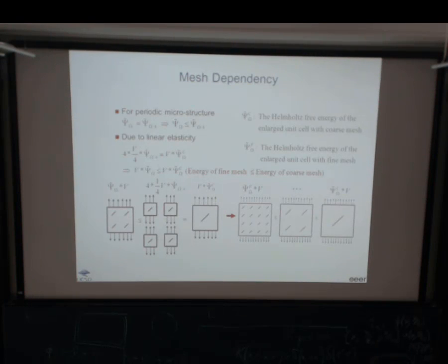So we try to use this to explain the mesh dependency. I know I'm going an unconventional route, but I think this offers a different explanation of why in damage mechanics there's mesh dependency in the numerical solution. So my explanation here is this. If I use the same damage law for the continuum, and I construct a mesh, and I model it, and I apply the law until the structure fails, you refine the mesh, but using the same damage law, same material constants for the damage law.